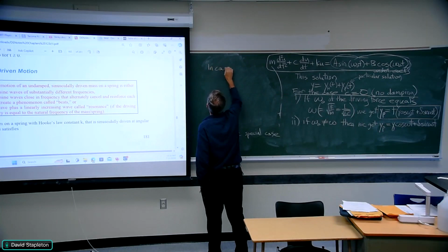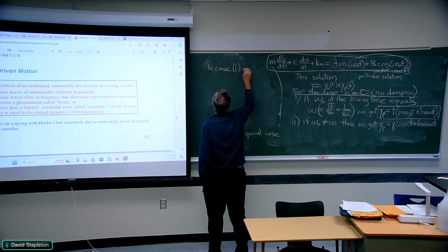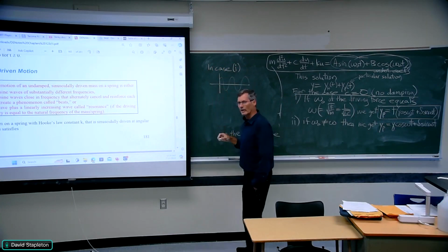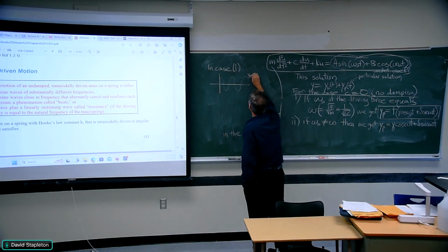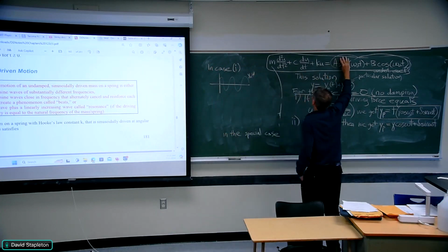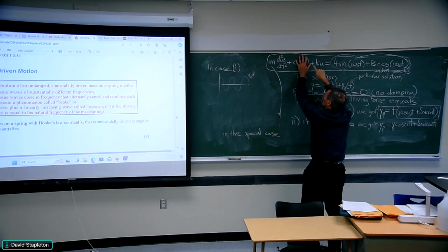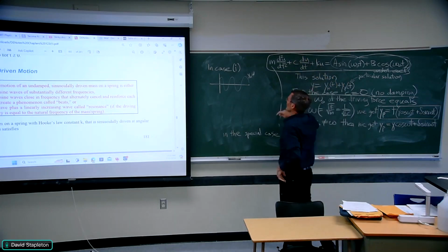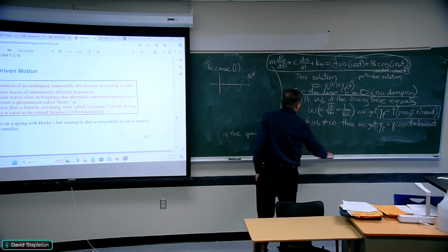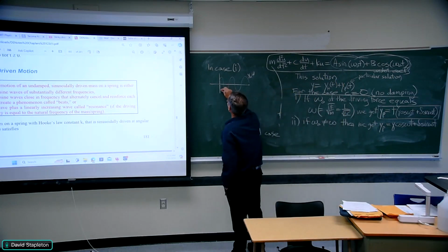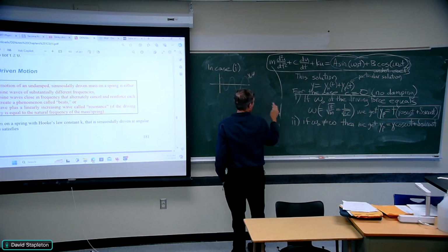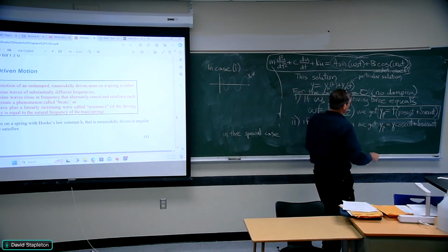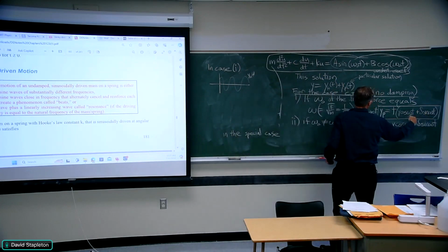In case one, you get the homogeneous solution as a sine wave because it's the undamped, right? Y_H of t is the homogeneous problem where you didn't apply force, and with C equals 0, it's just the mass on the spring with no damping, and so that's Y_H of t. But in case one, the Y particular solution is the same frequency and multiplied by t. So here's a constant times a sine wave times t.